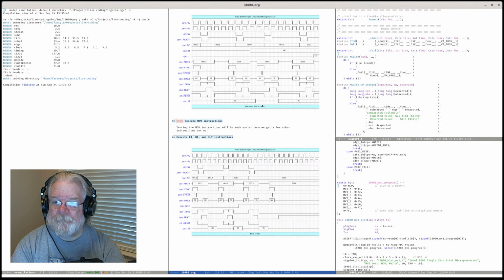Now, if this were the actual kinds of logic analyzers that one used back in the late 80s and early 90s for microcomputer design, there would be a facility in it that says, oh, I recognize these instruction cycles for the 8080 because I am an 8080 logic analyzer. And it would actually substitute for these numbers. It would say this is a fetch. It would say this is a MVI into the B register. So it would put the opcodes out.